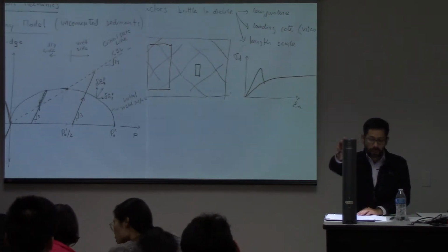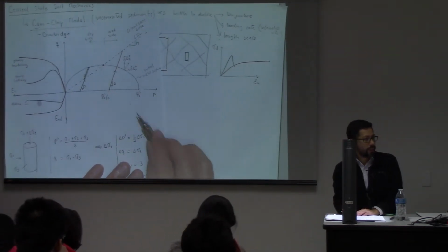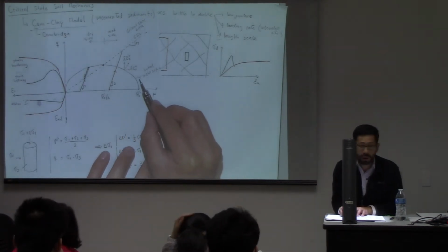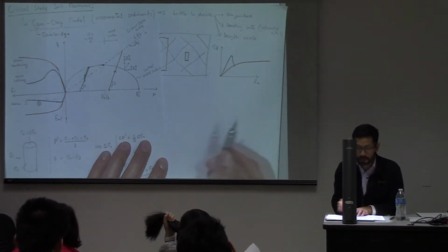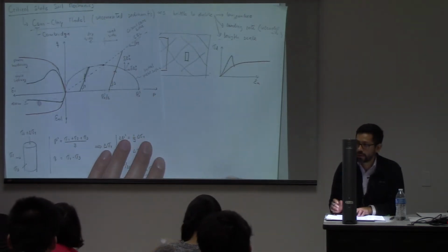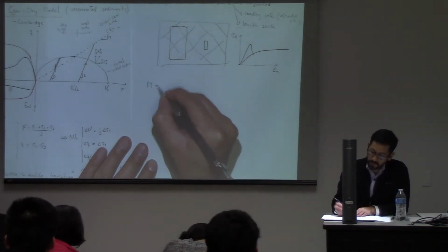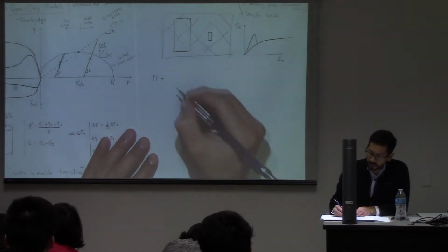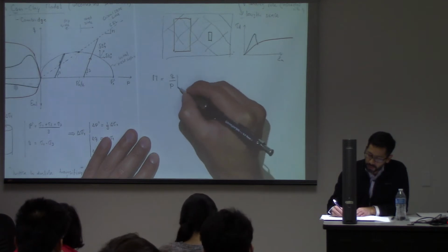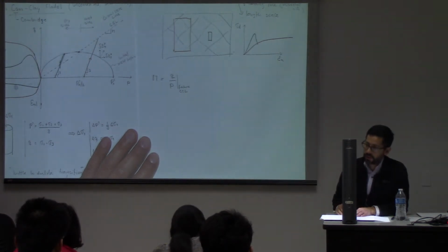All right, so we know now what are the new surfaces that we need to take into account for this elastoplastic model, and we know what is the basic response depending on where you do the loading. So let's write the equations now for these two surfaces. What is going to be M? M, by definition, is going to be the ratio of Q over P at failure or at the critical state line, right?